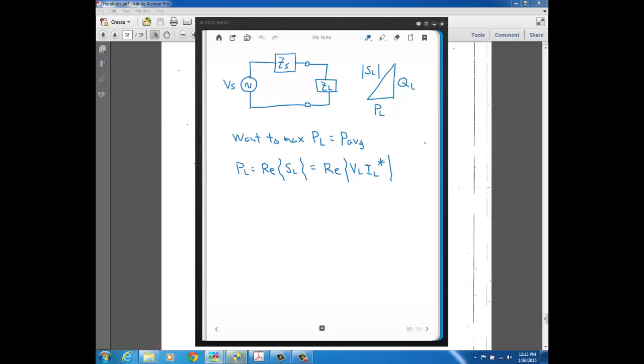to an impedance load. So just like the DC case, we have a Thevenin equivalent at 2 nodes here, but since it's an AC circuit, we have impedance instead of resistance, and then we hook up an impedance load. And you know from previous discussion that the power triangle is a convenient way to find out what you need to find out about power in an AC circuit. So here we're using L for load, and just like we talked about, the real part is your P average, your absorbed power. The imaginary here is your reactive power. So again, this is Q load, not inductor. L stands for load here, not inductance.